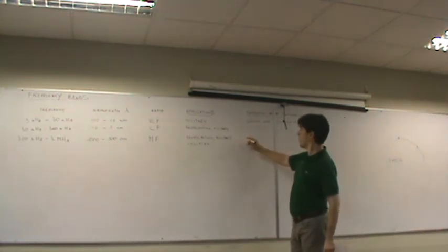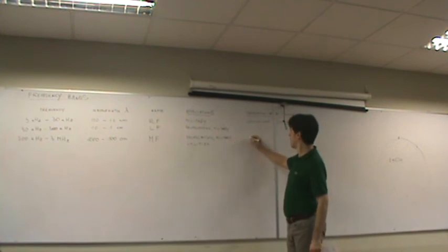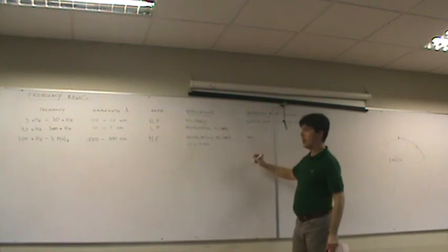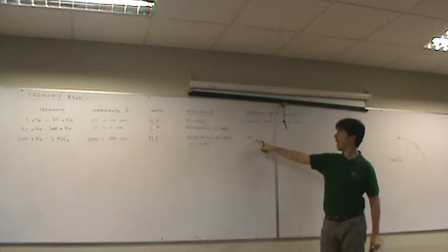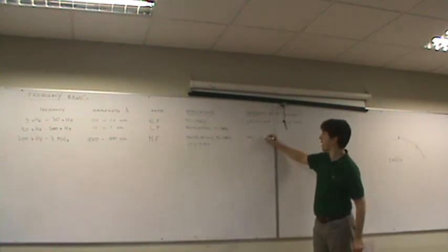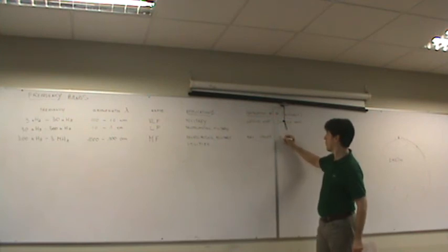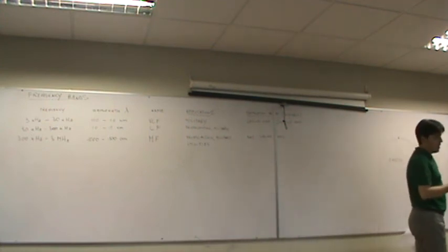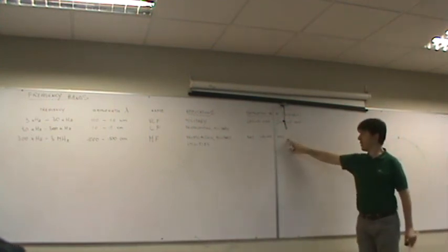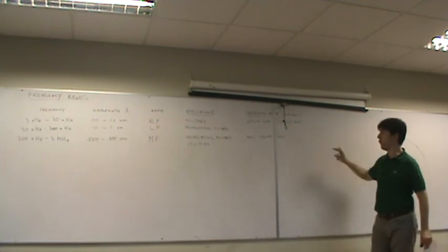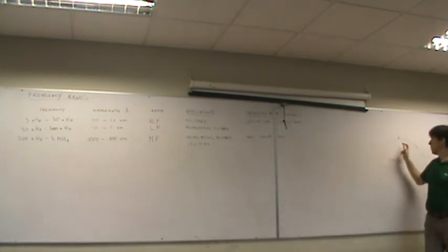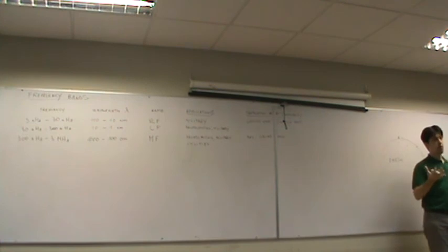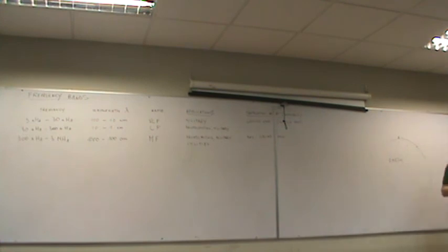Now this band is interesting because during the day the main propagation mode is again ground wave, surface wave. But the attenuation is stronger. The attenuation of the surface wave increases with increasing frequency.